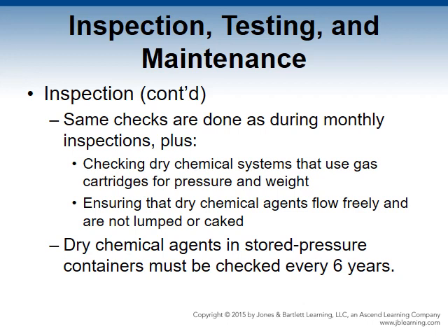Every 6 years, any dry chemical agent in a stored pressure container must be disassembled, the container inspected, and the dry chemical agent replaced.